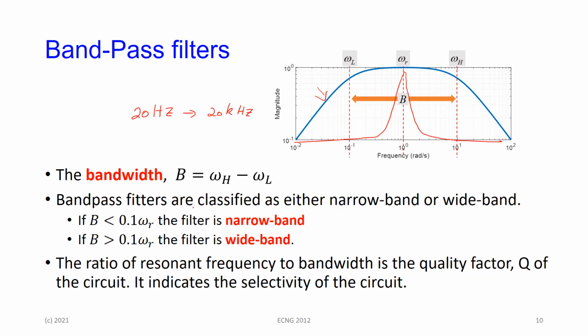So what I would do is that if I am processing audio for a recording of some sort, in a recording studio, you have the microphone set up in the studio. What you would do is to pass it through a bandpass filter that isolates this and sends this forward and rejects everything below or above.